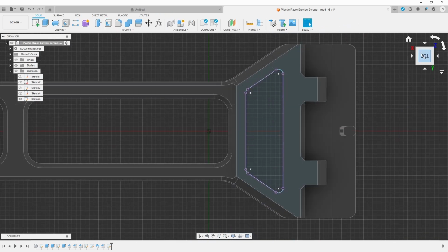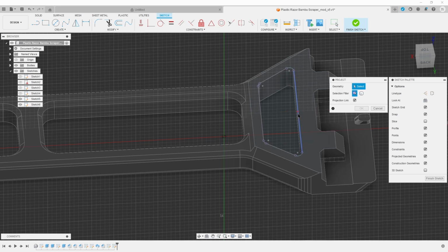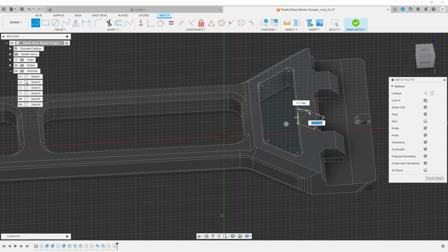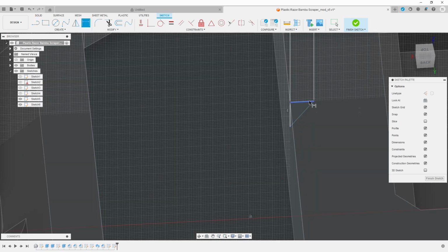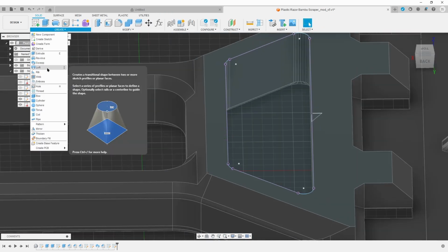So we finish that sketch. Here's our path. We're going to create another sketch. We're going to create it in plane. And we want to create, in this case, I'm doing a chamfer again. So we're going to control the depth of the chamfer and then the angle, set it to 45 degrees as before. And it won't sweep properly.